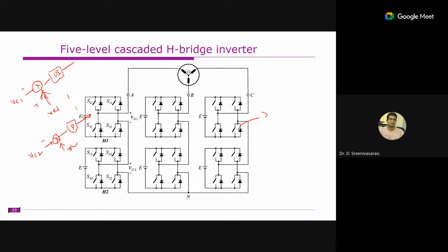Depending on that, we need to properly handle these outputs of the PI controllers. So cluster balancing controls the entire phase leg at a time, while in individual voltage balancing each capacitor has its own PI controller, for A phase, B phase, and likewise.